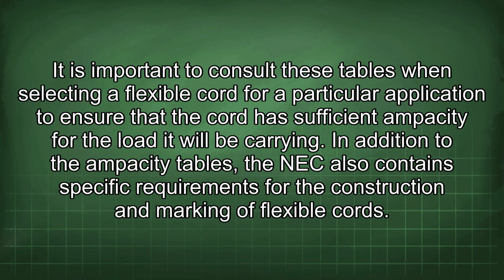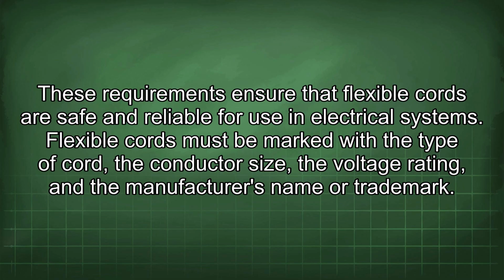It is important to consult these tables when selecting a flexible cord for a particular application to ensure that the cord has sufficient ampacity for the load it will be carrying. In addition to the ampacity tables, the NEC also contains specific requirements for the construction and marking of flexible cords. These requirements ensure that flexible cords are safe and reliable for use in electrical systems.